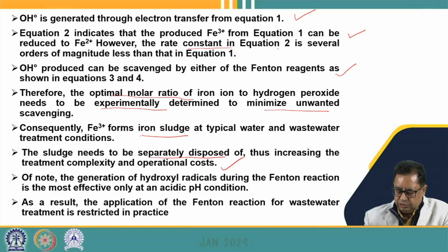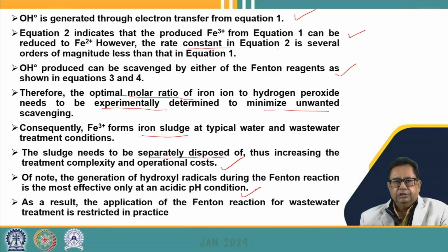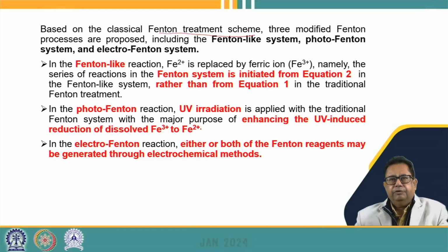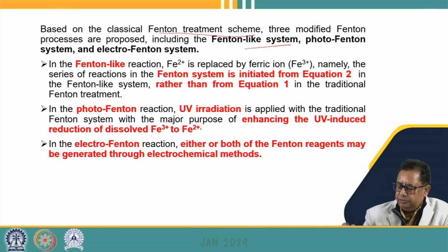So this means that the hydroxyl radical generation in the Fenton reaction is most effective at acidic pH conditions, and as a result the application of the Fenton's reaction for wastewater treatment is restricted because of the above complexities. So based on the classical Fenton treatment scheme, that is, we are having the ferrous and we are having the H2O2, we can also have certain modified Fenton processes which are proposed and which can enhance the efficiency of the Fenton's system. For example, we can have Fenton-like system, photo-Fenton system, and electro-Fenton system.